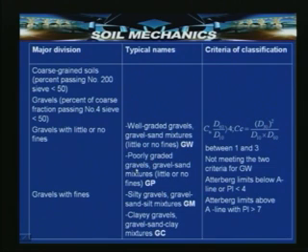Poorly graded gravels, that is poorly graded gravels or gravel sand mixtures, little or no fines, is GP. That means if you are not able to meet this well graded criteria, that is, it is not meeting the two criteria, Cu greater than 4 and Cc between 1 to 3, then it is called GP.